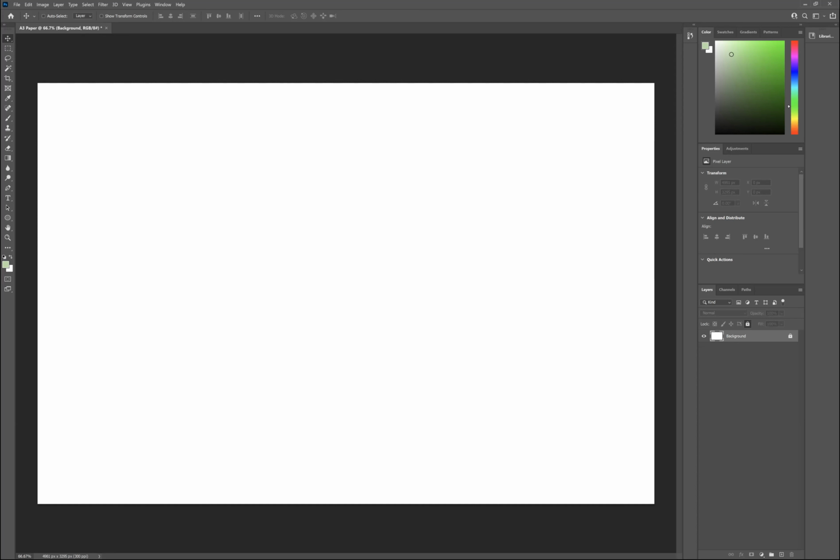Anything I change or I do will not take place on the locked layer, which is very helpful in some cases. At the bottom of these layers, you can see that I can edit my layer. So I can either delete a layer. Now, because this is locked, I cannot delete it. If I unlock it by pressing on the icon here and click on OK, I can delete my layers and start altering them. I can also press on the plus sign where I can add a new layer. So this is layer 1. I can add as many layers as I want.